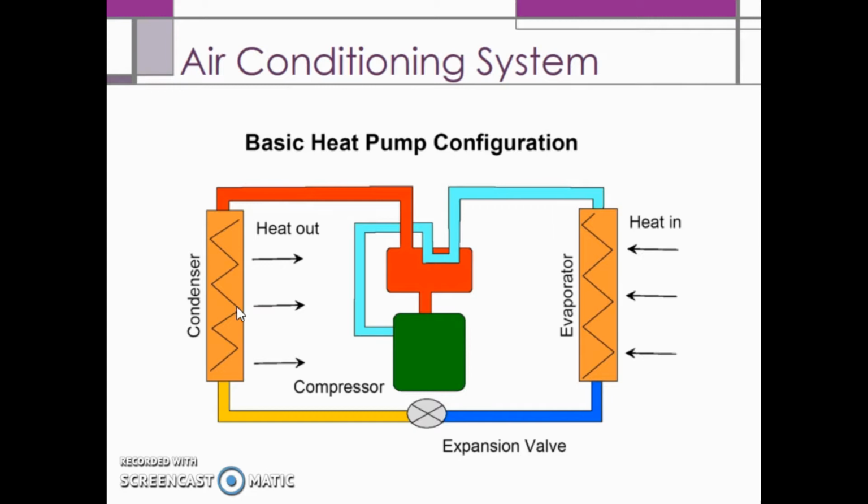As the gas goes through the condenser and cools, it condenses into a liquid. Then the liquid goes through an expansion valve, which serves as a pressure drop valve. There is high pressure on the condenser side and low pressure on the evaporator side. Due to the pressure drop, the temperature also drops. In the evaporator, the liquid evaporates back into a gas and absorbs heat. This is located in the HVAC module in your car, which then cools the cabin of your car.